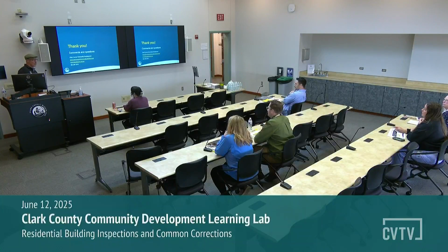If I fail my final inspection for something minor, can I still start moving in? As long as there are no fire life safety issues, we typically don't have a problem with issuing a TCO. But if there are other parties involved, we would want to make sure, for example, fire sprinklers, that would be considered fire life safety. So if the fire marshal hasn't signed those off, even though with the building department you just got 3 or 4 minor corrections, one of those would be to obtain final fire. And so fire life safety always has to be taken care of before we can do a TCO.